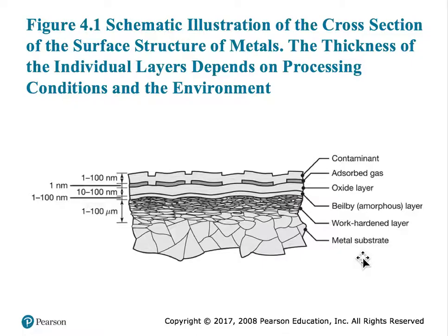And if you remember in the last class, we talked about one of the most important properties that we need for materials, its fatigue resistance. And how do you improve the fatigue resistance? You have to do a lot of different kinds of surface treatments such as case hardening, ion nitriding, or shot peening, etc. All of that improves the fatigue resistance of the components. But how do you correlate that to the surface quality?